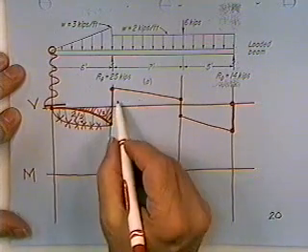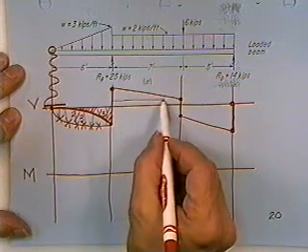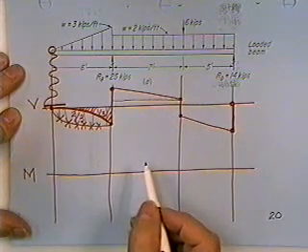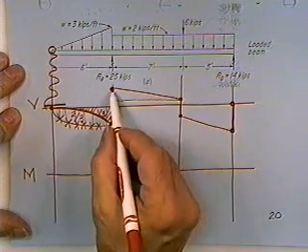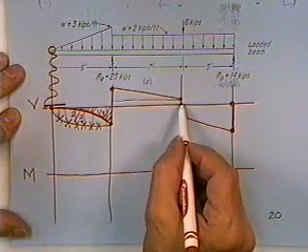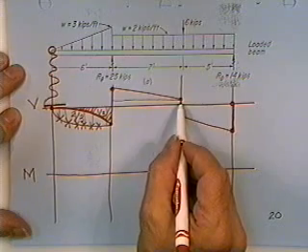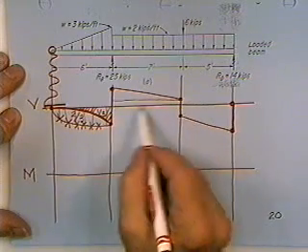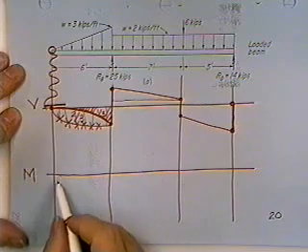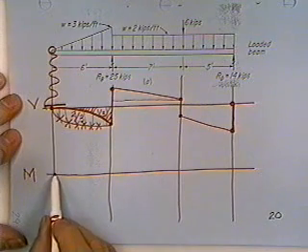These areas are easy to calculate. If you like, you can break it up into a rectangle and a triangle. Some people just like to take the end heights and average them: sum them together, divide by 2, and multiply that times the base. That'll work nicely.